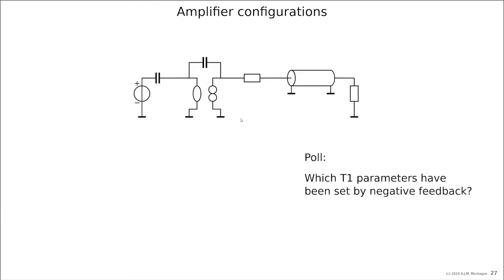So then we have a last one, which is here just sensing the current of the antenna, making a transimpedance amplifier, which is now integrating because, as in the previous case, the antenna voltage to current is differentiating, so then integrating, then we have an instantaneous transfer again, and then we just make a brute force output impedance again by placing a resistor in series with the amplifier. This is for the people who did the antenna amplifier in the third year. This is the structure that we have chosen in the previous course.